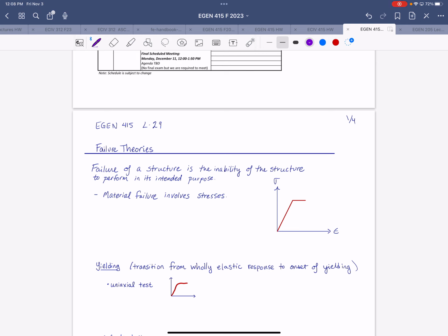Doesn't the dummy load count, I guess the fictitious, not the RB? I see. So let me think. You'll already have RB in terms of QL and L, but it needs to be in terms of QL and Fi. Yeah, you want that in there too. There's a couple ways you could do it. You could do the Castigliano's method again with just Fi and then superimpose the results, or you could use a beam table and superimpose those results, basically.